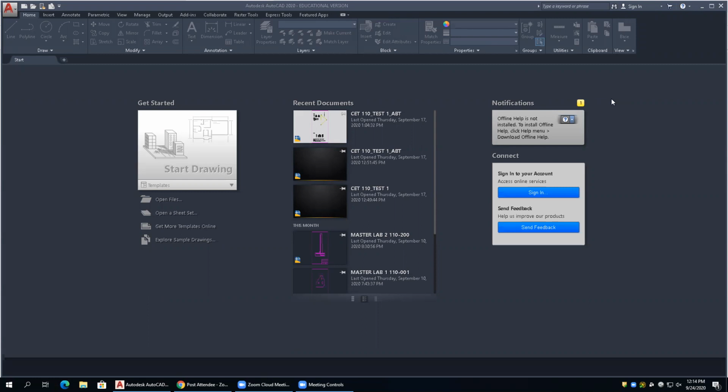It's not unusual to have, say, 200 layers in a drawing, maybe 1,000 layers in a drawing. So for instance, if you were mapping something out in the real world, you could have your pavement on a layer, your center line on a layer, your sanitary sewer on a layer, your trees on a layer, sidewalk on a layer, buildings on a layer. You get the idea? I mean, to infinity. So what we do is we fracture that out, and then we can look at subsets of that drawing. So we're going to look at how we create layers, what their properties are, how we manipulate them,